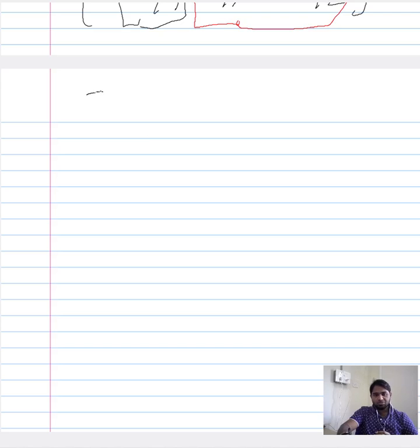So we have seen that whenever we have talked about the shear stress, we expressed it in this manner. So it comprised of 2 components. At least for the sake of our discussion, since we are talking about a random shear stress, let us talk in terms of x and y. Whenever we talked about a shear component, particularly in 3 dimensions, we ensured that there were 2 subscripts for each shear component. The first subscript represented the plane, the second one represented the direction.